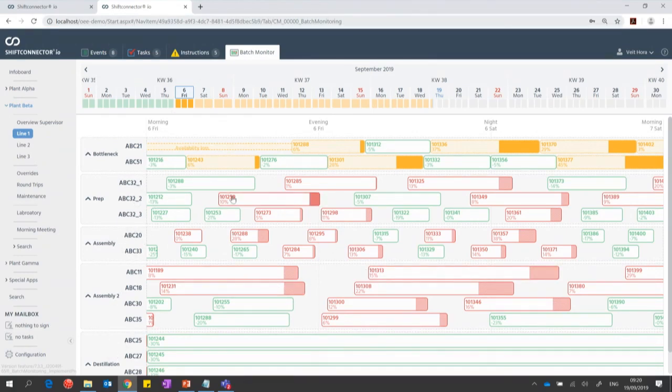And also here we have the same system. So we have here unit procedures which come from event frames from PI. The green ones are actually within the reference time. So within, let's say, the best 5-day average, if that is your target. The red ones, they actually exceeded that target. But the yellow ones are the ones which actually held up the process, which now need to be accounted for by the operator, which now need context from the operator.